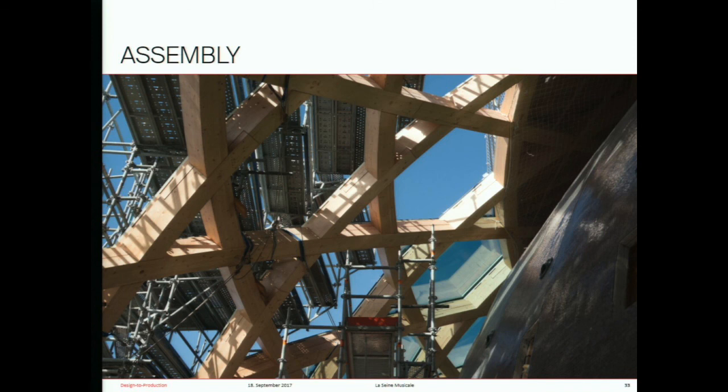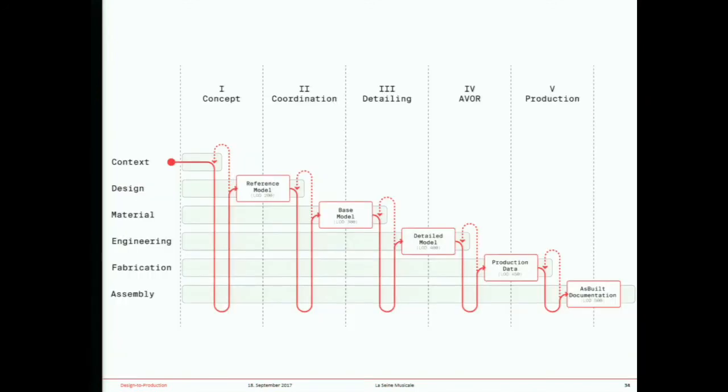And at the very end of the construction process, we reached the upper concrete ring, which is located 27 meters higher than the floor level. I told you earlier that we did not need any scaffolding. Also, you can see one here, and this one was actually used by the facade team to place the facade elements on site, which did not make the structural engineer very happy because this was not calculated for it. And this actually reflects the fact that we had very little contact with the facade team.